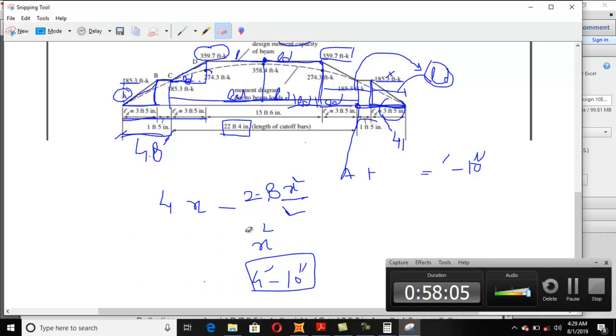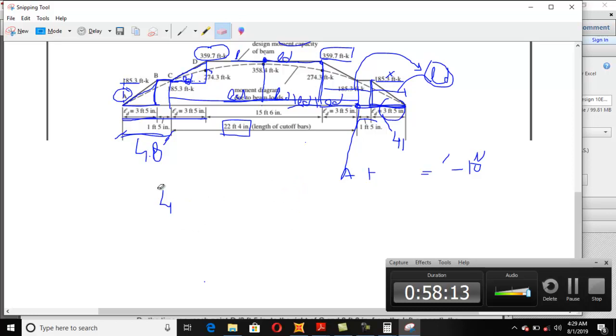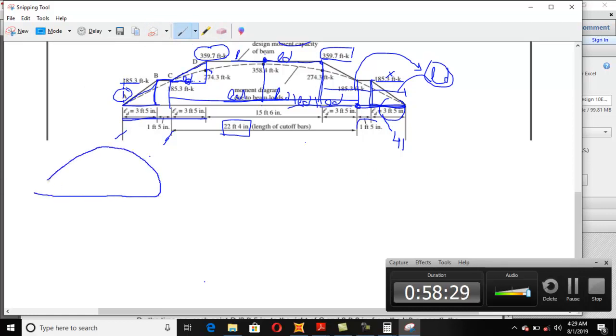You can draw it in SAFE, you can draw it manually as you read in engineering mechanics, and then you need to draw the moment capacity diagram, which is based upon your ACI and 0.9 and the basic formula. Once you draw your actual moment diagram, clear, and then your capacity diagram, clear, which looks somewhat like this as in the present case.